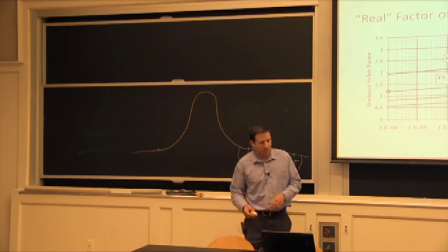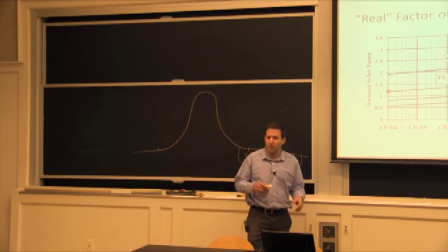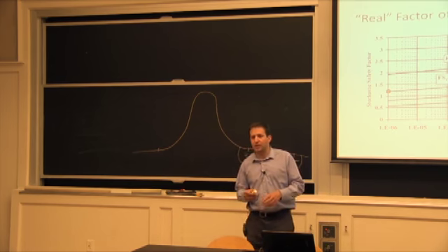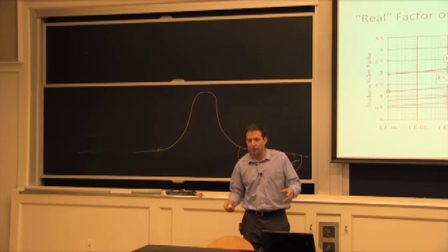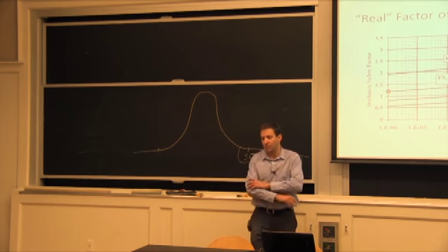There's a safety factor of 2, but then you also take the low material properties into account, and they have some criteria for figuring out the load and the wind load, and it's got a lot of complexity built into it. But in the end, they still don't want to make that bridge twice as heavy as it needs to be. It's just not the case. It's already very heavy.